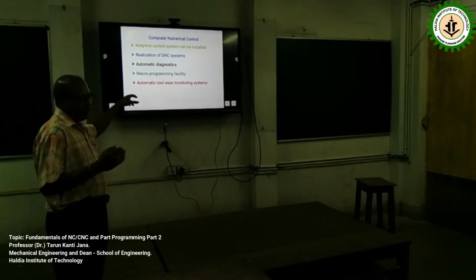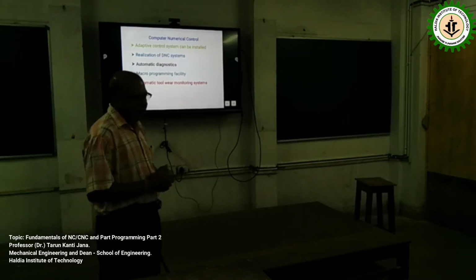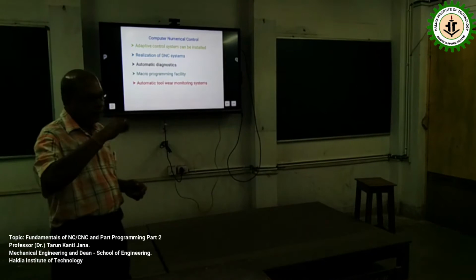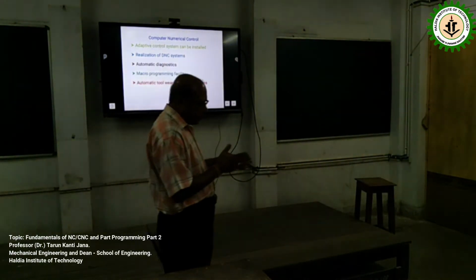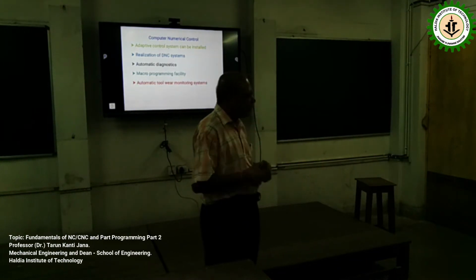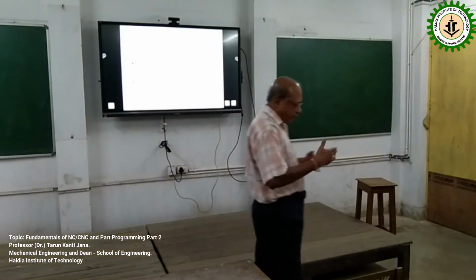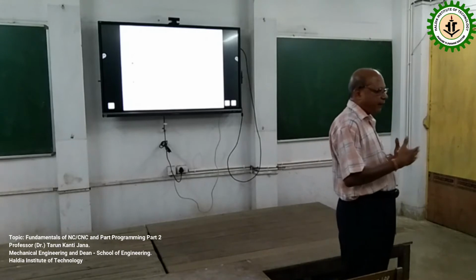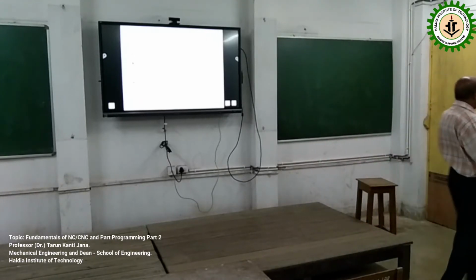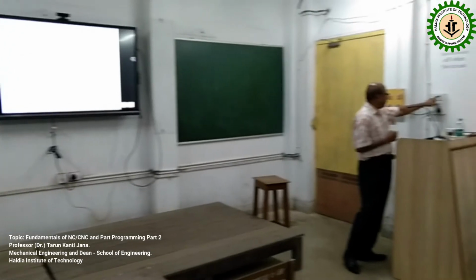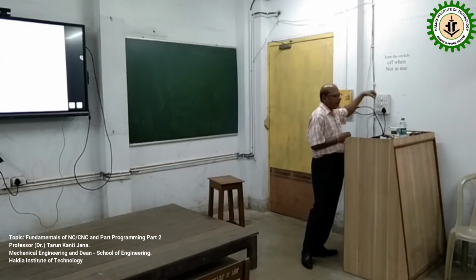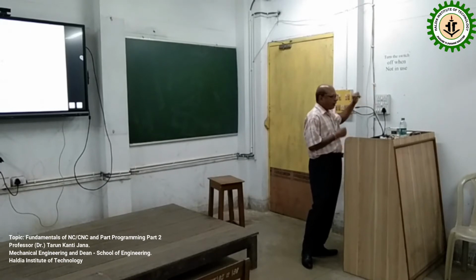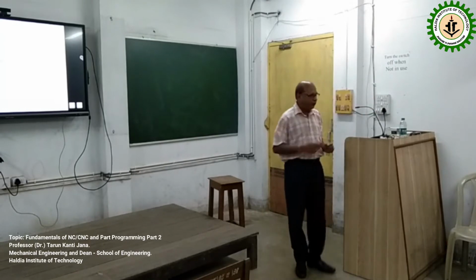Macro programming is a higher order programming facility. Here we explicitly specify the dimensions or the coordinates. But if similar types of jobs need to be carried out where the relationship will remain the same, just for instance, this is one block having some specific size. Now we scale it up 3 times. I would like to maintain the same proportional gap in the new job.